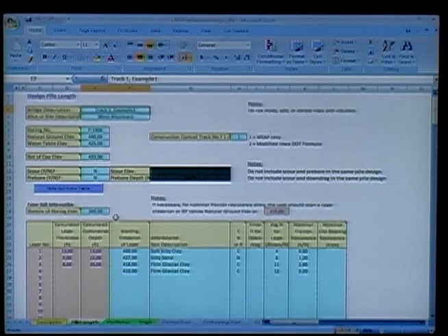And you go, well, you might hit rock first. It's probably good soil, at least as good as the stuff you've seen, and probably better. Are you going to go and do more borings? Probably not on your typical bridge. So we have talked to the soils office, and hopefully we'll get a little better correspondence on how deep the boring should go in the future.